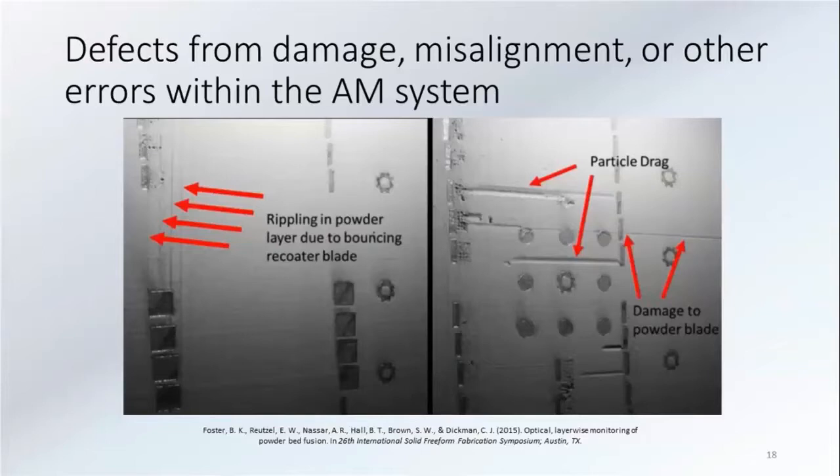build plate. A lot of the machines nowadays have a feature in there where you can just turn off a part, where you stop lasering it. And that is overall your best solution. So you'll have a grid of parts, and if you see one that's going wrong, you just say stop, kill that part, and keep going on with your whole build.